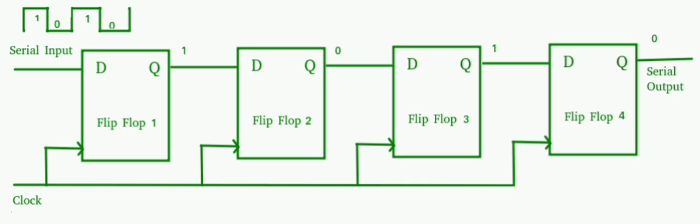Static RAM, data is stored like a flip-flop. Dynamic RAM, data is stored in a MOS capacitor. Static RAM, BJT or MOSFET is used. Dynamic RAM, MOSFET is used. Static RAM, faster. Dynamic RAM, slower. Static RAM, power dissipation is more. Dynamic RAM, power dissipation is low. Static RAM, density is less. Dynamic RAM, density is high.